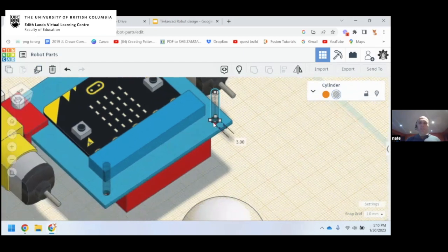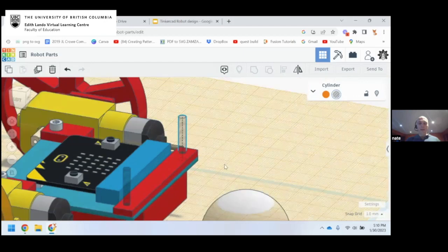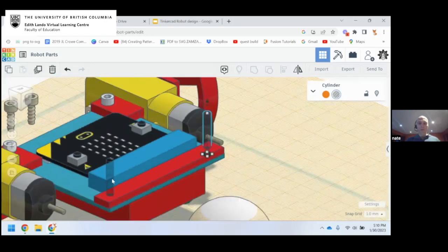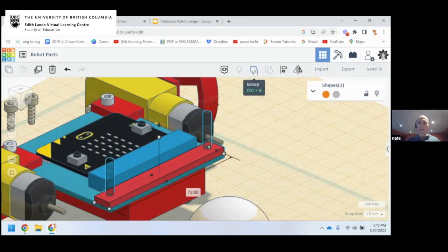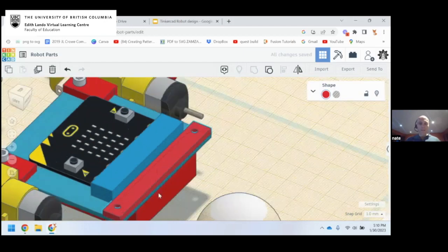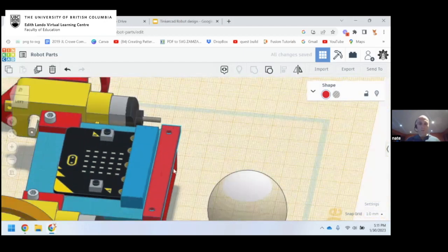Now all I need to do is click on the light bulb, and that brings back my piece that I was working on before. So I've got my 2 booleans, negatives, and I'm going to hold down shift. I'm going to click that one, and then I'm going to click that one. And then finally, as you remember, you need to click your solid piece on the bottom to solidify the entire thing. And then I'm going to click on group. And that's going to cut that out and give me those nice holes that I want before.